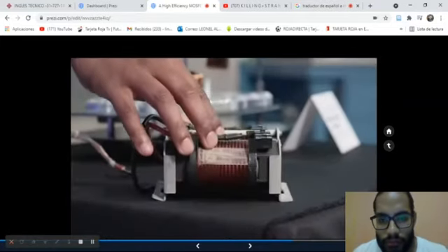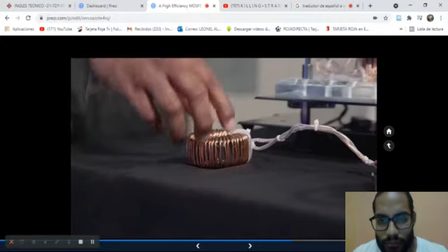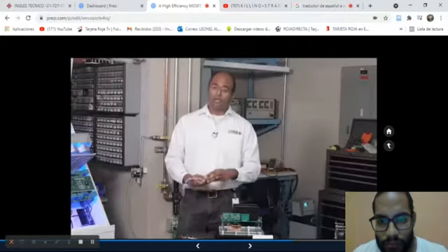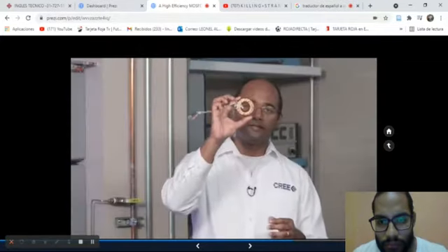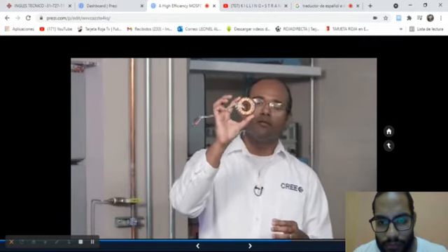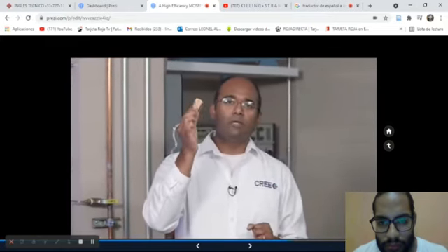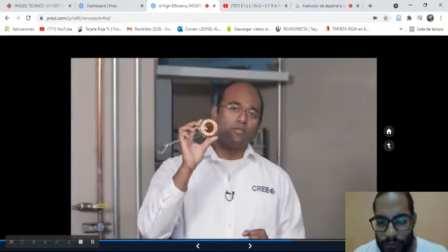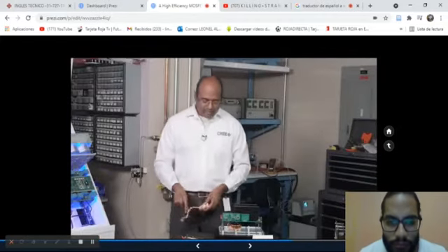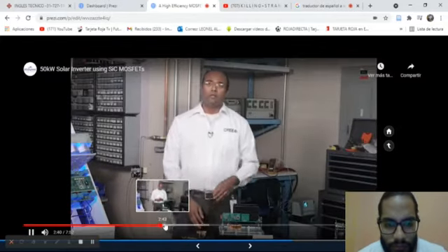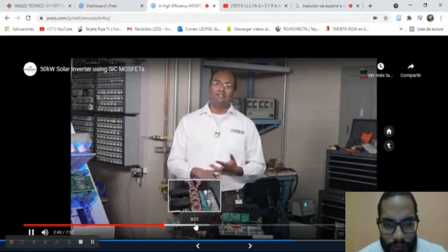But when you go to a 100 kilohertz switching frequency, you end up with a boost inductor that looks something like this, about the size of a small donut. It weighs 0.4 kilos. So going 5x in switching frequency actually reduced the weight of the boost inductor by more than 5x. And that's really where most of the cost, weight, and size savings comes from.